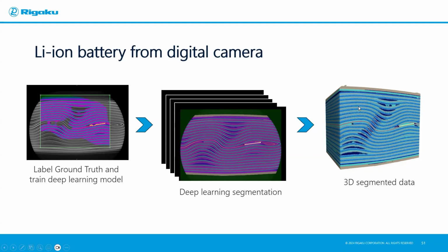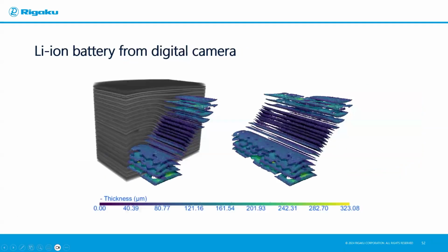So we can look at the thickness of perhaps those layers, but in this case, I mentioned that we were more interested in this delaminated area. So this is a thickness mesh that shows the variation in thickness of this deformation inside, from something that's very thin, about 40 microns thick, to something that gets larger and wider as you go towards the outside edges of the battery, where it's like 5 times larger in that case. So this is something that we can easily do using X-ray CT.